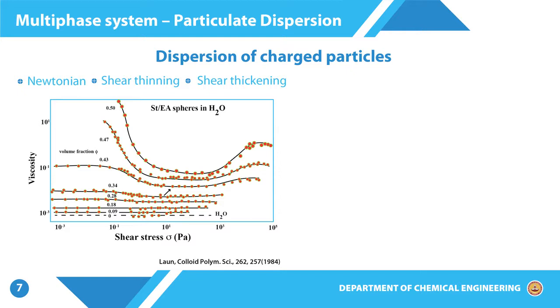However, the time scales of the processes are such that they are able to give us a completely dissipative and overall viscous response. Only when we start looking at higher volume fractions, so in this case for example 28 or 34%, we can see that there seems to be now shear thinning in the material over a very small stress range.